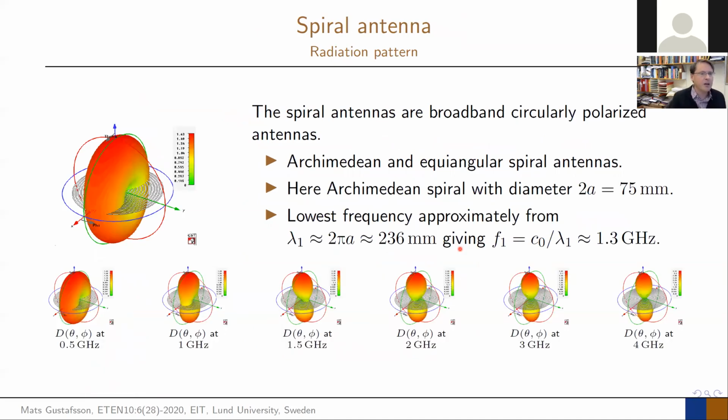If we look at some of the radiation patterns of it, here you can first see a very low one. At 0.5 gigahertz, you are below this resonance, and you can see this donut pattern that comes down. That's because this is an electric dipole. There are 2 separate pieces of metal. If you make it small, it will be an electric dipole. Whatever you do, you cannot avoid it; it will always come up. It doesn't work as an antenna, but if you were using it there, that is what starts coming in.